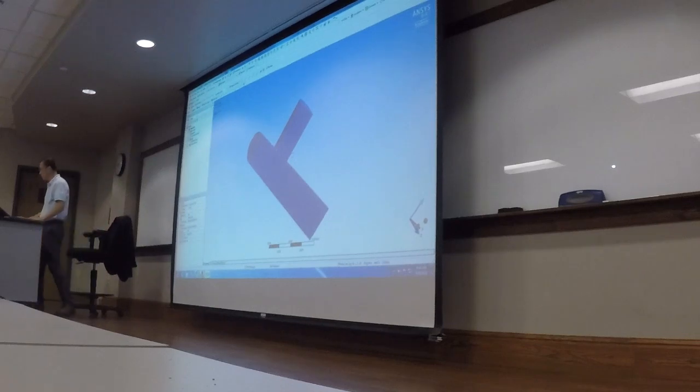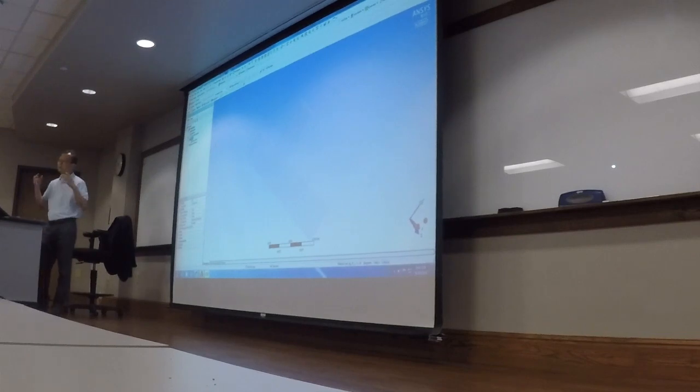So click on mesh again. We're going to do exactly the same as what we did for the tutorial. So go expand. You can make it up a little bit. So here, expand sizing. All right. Curvature normal angle. Make it 10.